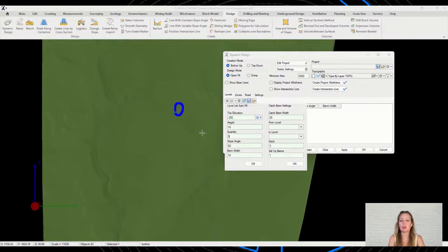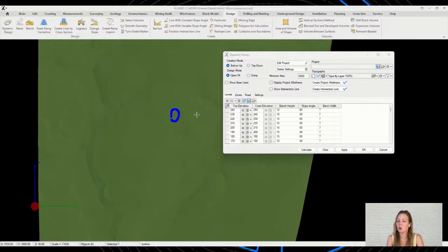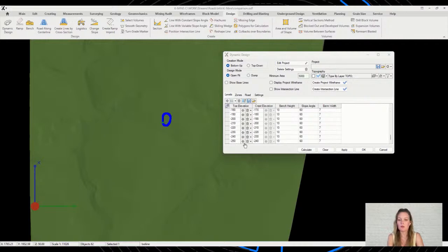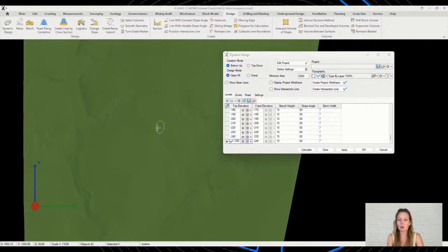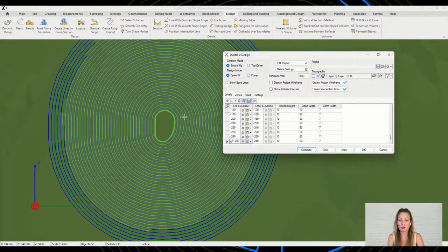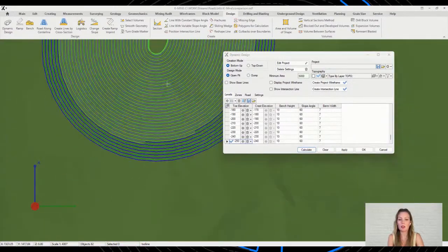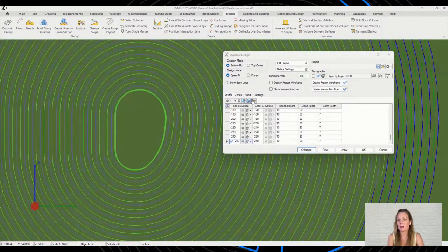As always, construction begins with determining the bottom of the quarry. Next, we create the necessary list of levels and begin construction. We assign the closed contour to a specific level and click calculate, and we'll get the contour of the quarry. This contour will be according to the list of levels without roads for now. We see that some of the wedge edges are above the topographic surface, which is good.